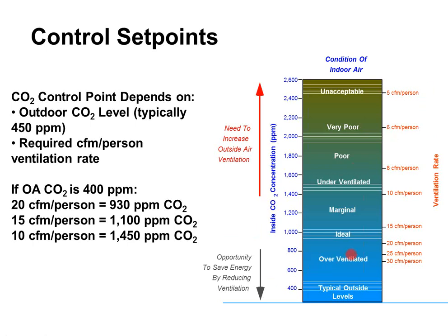But you can go to a building with a handheld CO2 meter, and have a couple of those meters, and they're pretty useful. And I can walk in somewhere and see it's 500-600 parts per million. Unless it's an economizer day, I know they're overventilating, right? And they're wasting energy. If I walk in there and it's 1400, 1500, 1600, I know they're underventilating. And it's probably smelly and stuffy in there. And then if it's up in the 2000s, then it's probably at the point where people don't even feel all that great. I mean, they're not sick, but they probably feel groggy and stuff like that.